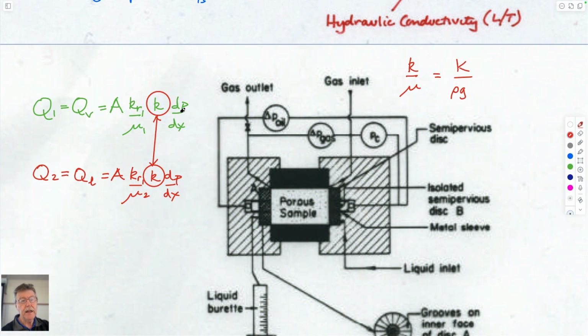They change with elevation and also the temperature. And it's convenient for us to use a constant to represent the characteristics of the porous medium and have all the influence of the fluid that infiltrates it contained within the viscosity. In groundwater hydrology, we tend to use hydraulic conductivity because it's measured at 20 degrees centigrade or 10 degrees centigrade and for water. So that hydraulic conductivity is a function of the fluid that's in it and its temperature, which defines its viscosity, and also these terms.